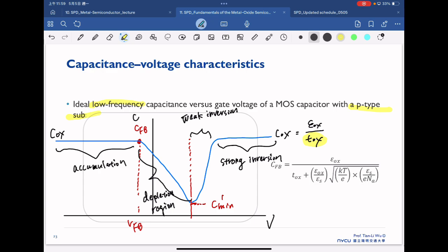But now if you just quickly measure the CV on your fabricated device and bias your CV in the inversion mode, then you can easily get a simple calculation of your oxide thickness. And this method is widely used in the semiconductor industry nowadays, even for the future.